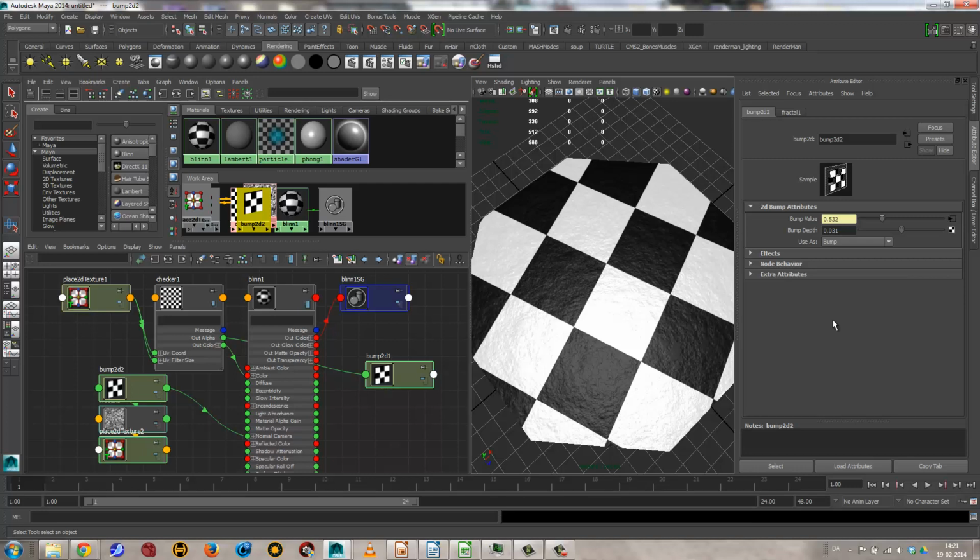There's also different types of bump mapping. You can also use normal mapping, either tangent space or object space. A quick way to explain this is tangent space is based on the surface itself, object space is based on the object. So tangent space will work when models are deforming, and object space will only work for rigid models. If you can get away with an object space normal, you'll save a slight amount of computation.